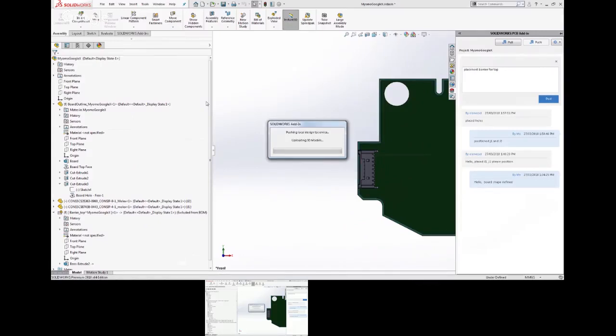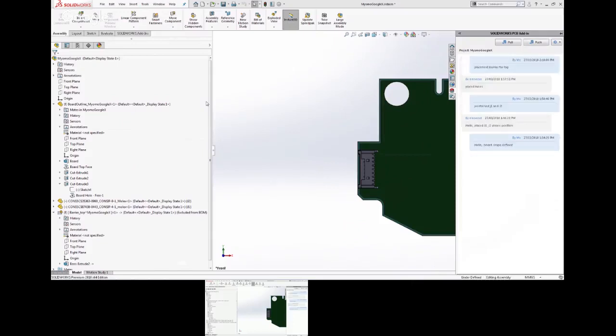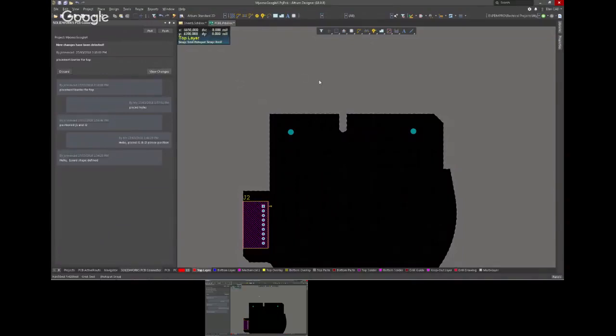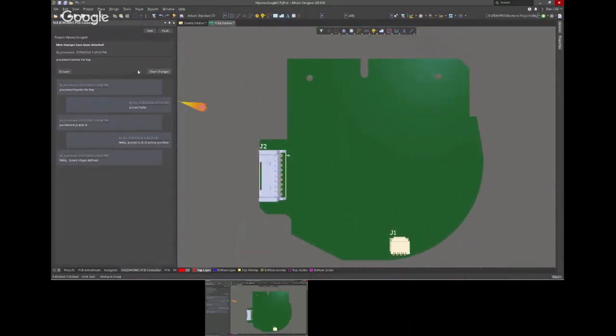Today, with the electrical, we have to import the step file. I have to bring in a step file that represents a block, or usually it's done through a drawing. I look at the hashed area and say, okay, I cannot place components there, and I end up drawing that keep out myself on the electrical side. Now with the new change, I'm going to place it in 3D mode so you can see it.